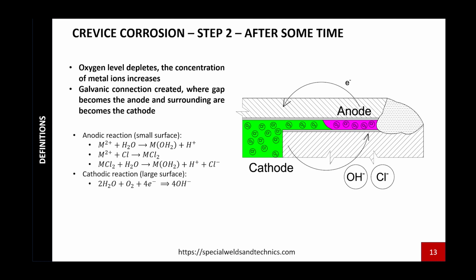As I mentioned before, we have in this trapped seawater some oxygen and a lot of chloride ions. To have a passive layer on a stainless steel surface, we always need oxygen. Stainless steel materials have a lot of chrome alloy inside. The chrome and oxygen create this passivation layer, which provides corrosion protection.